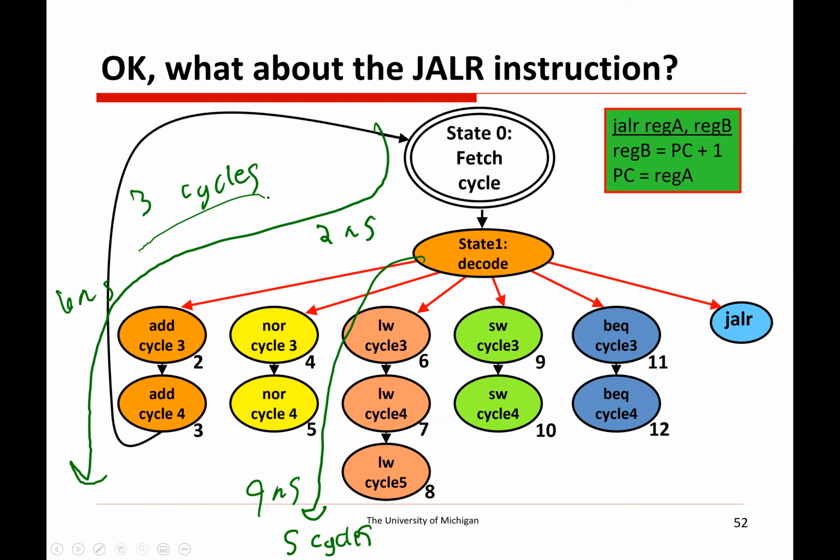So it really is just the granularity of when we can start and finish instructions. That's the benefit of having a shorter clock period. And if we're doing a bunch of adds, we can keep ending multiple cycles early. If we're doing single cycle, we can't end partway through a clock cycle. Cool.